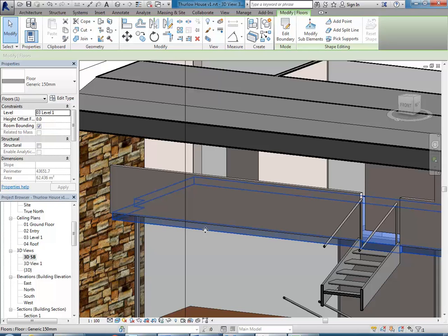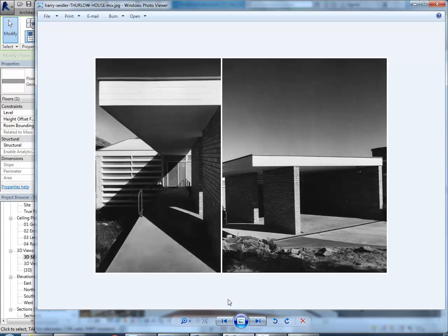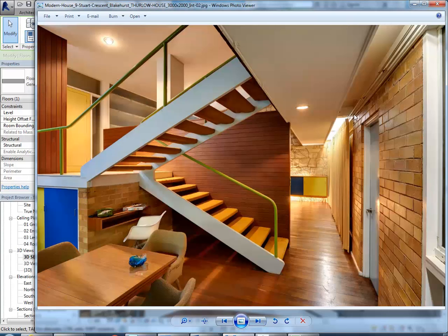And so the floor joists will usually be at least 150, but we can say here it's not spanning all that much, so there might be a little bit less than 150, which gives us room for the floor lining. So just want to think about that before you go too far with the next part, and make sure you've got enough thickness. So 150, I'm going to say for this building that's okay, because it doesn't span very much there.